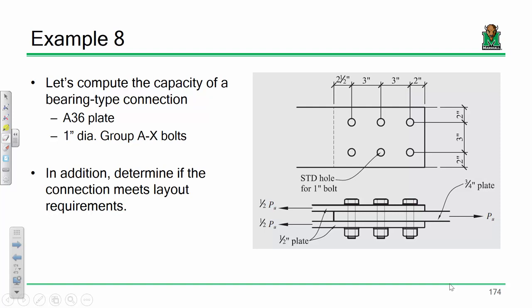480.6. That's the bolt shear. I'm talking about bolt bearing. Okay, so one of them was 457.7. What was the other one? 558. Okay, so one of them governed and one of them didn't. So ultimately we found that the first case of bolt bearing governed the capacity of this connection. I think that it was the center plate that was ultimately going to fail in bolt bearing. Am I right on that?